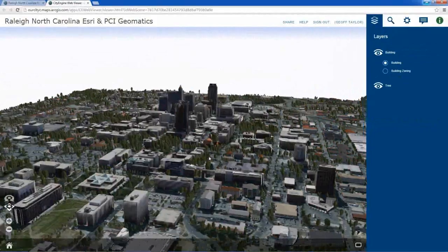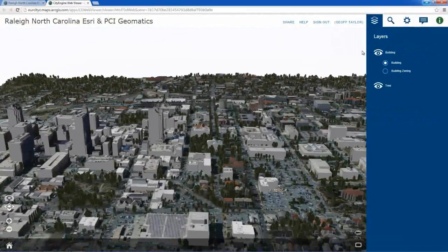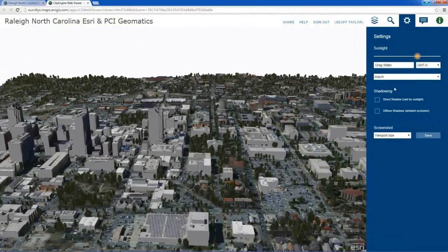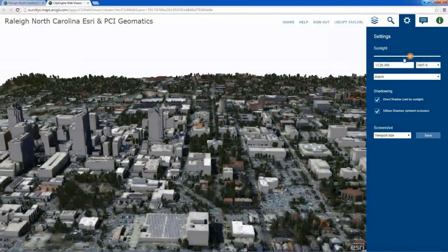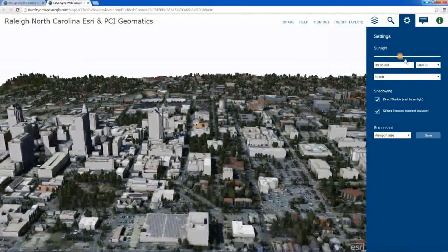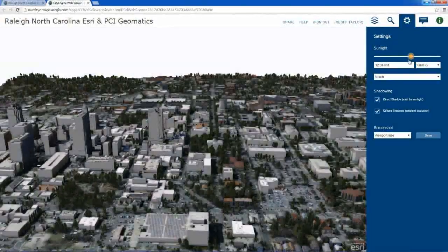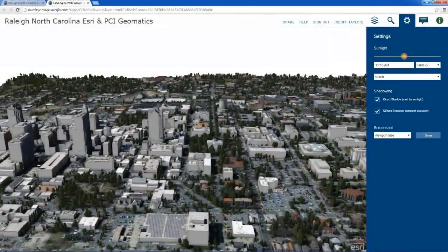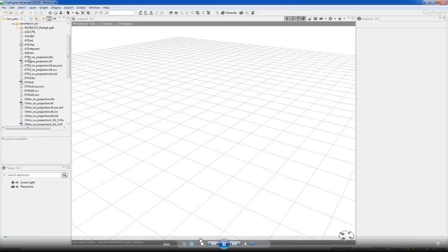So again, these are the models generated in 3D FeatureXtract and CityEngine, mosaicked, we could say, together with our existing data, or combined. And with that, it allows us to get more accurate height study visualizations. You could also use the 3D Analyst tool to do similar analysis, but this allows anyone to do 3D analysis on the web. You can use a comment tab here to make comments in 3D and some other capabilities, or even query your building information.